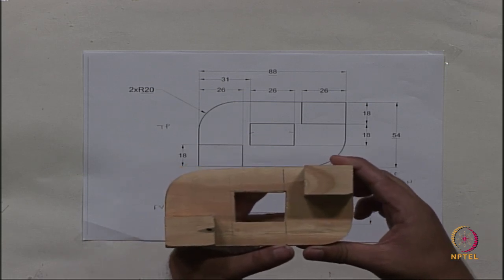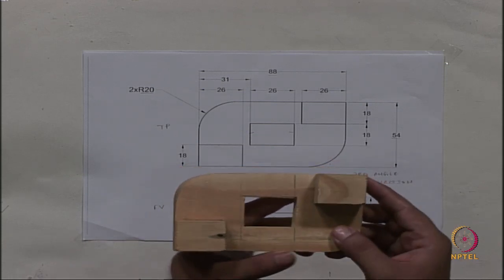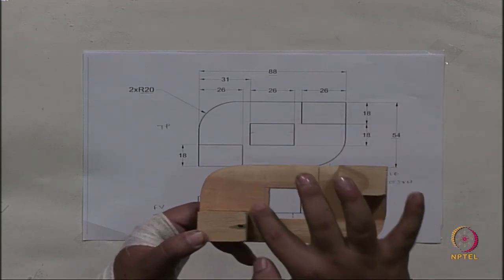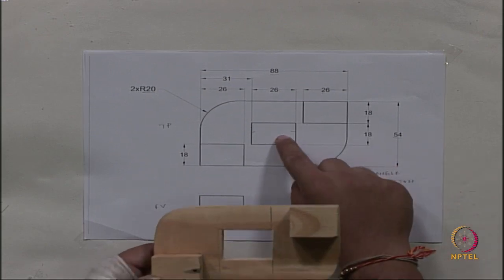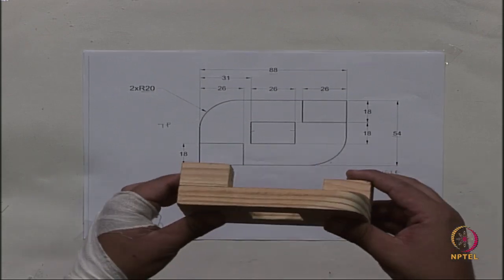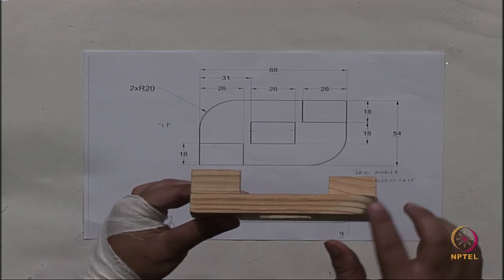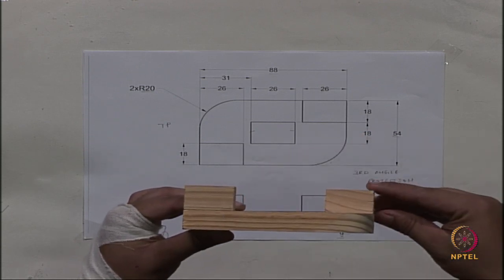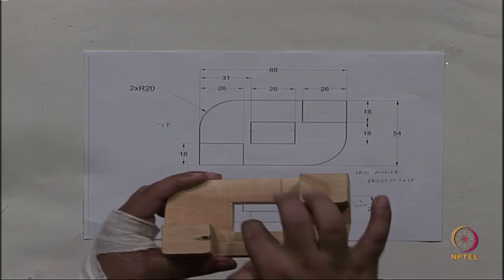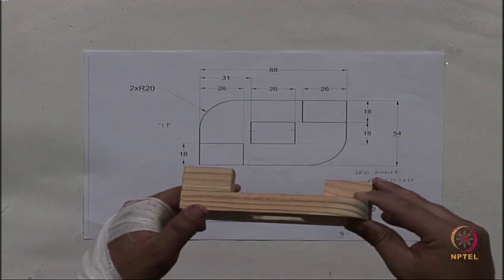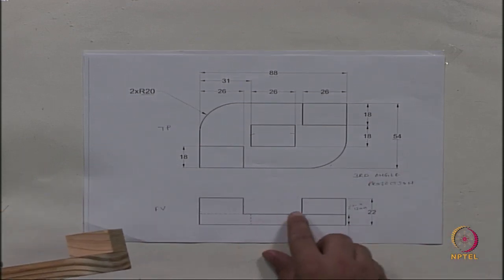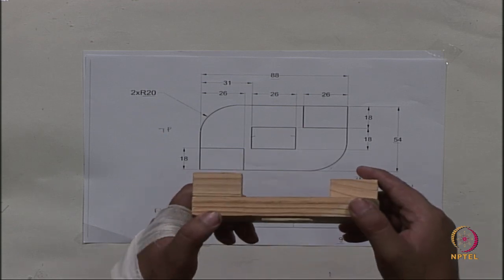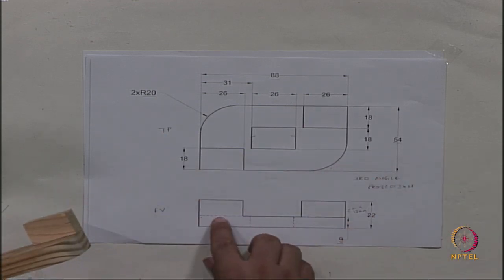Now, this is the top view. As we can see in the top view, we have this rectangle, these two small rectangles and this rectangular cut. Now, this is the front view. In the front view, we can see the thickness of the slab and the thickness of protrusions, and since this edge will not be visible in the front view, we have the dashed lines. Additionally, this edge will also not be visible on seeing from the front, so we have this dashed line.